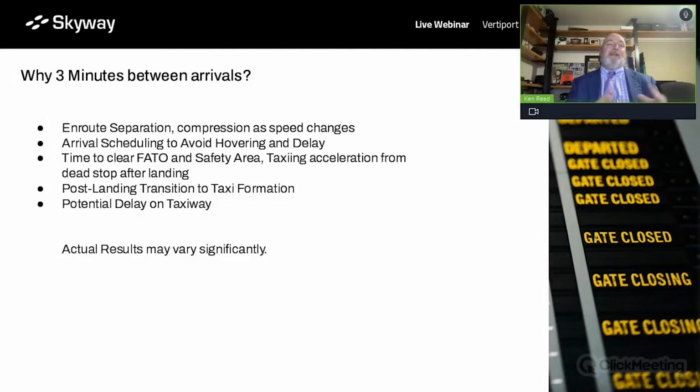So we think that because many of these flights, these air taxi type flights, will occur in a community, and those flights will typically be 20 minutes or less, that we will be able to schedule the flights in a way that a VTOL aircraft will not depart from its departure vertiport until it has an arrival time scheduled at the destination vertiport. And we have to give that a little bit of time, a 3-minute window perhaps, to make sure that we schedule that properly.